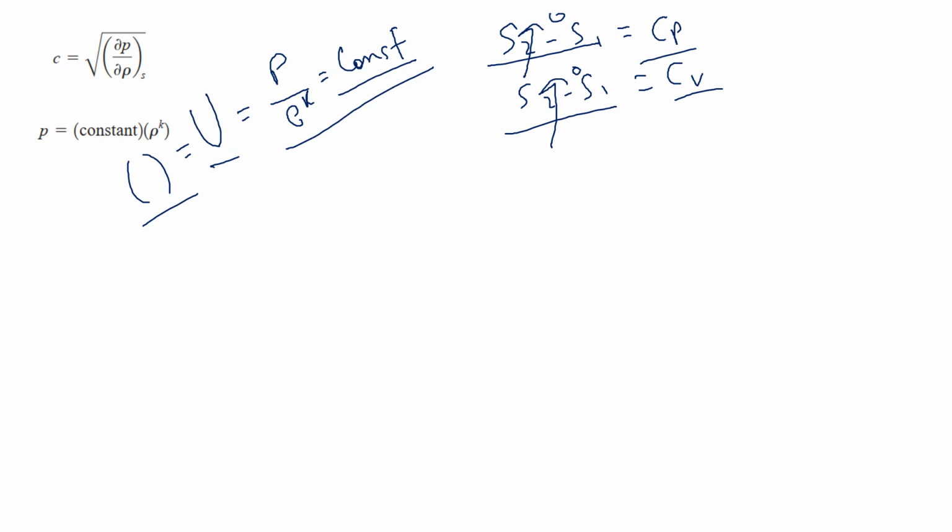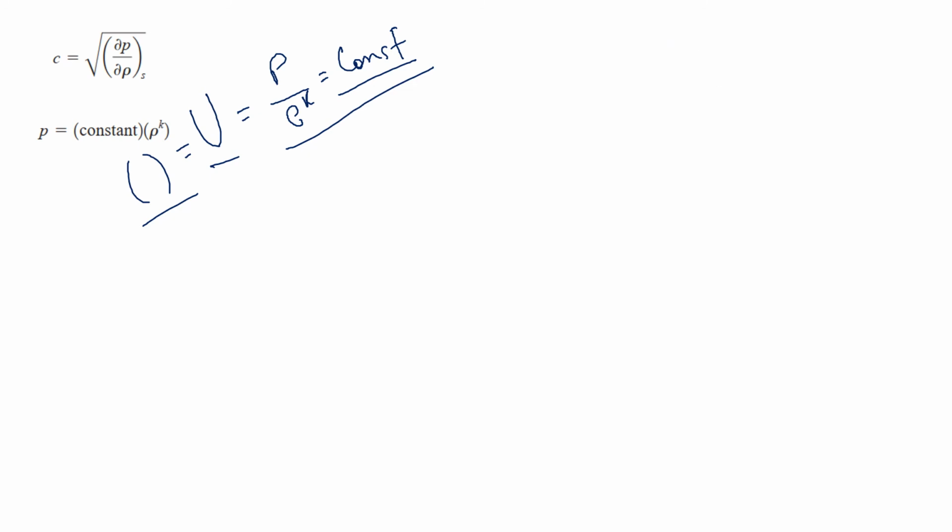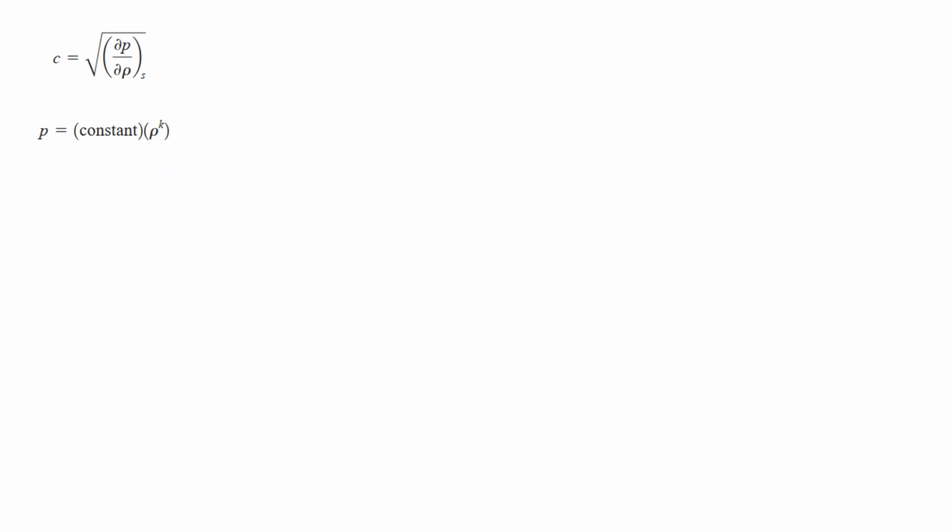Then we compared these two equations, and we had a term in which the density, pressure and temperature were all related to a constant. That was a very useful term, with which we can find the change in density with respect to change in temperature, and the change in pressure with respect to change in temperature and density. That was only because we considered an isentropic flow situation. Considering that isentropic flow and using this equation, we can derive another term for the speed of sound, which also includes the pressure and temperature effects.